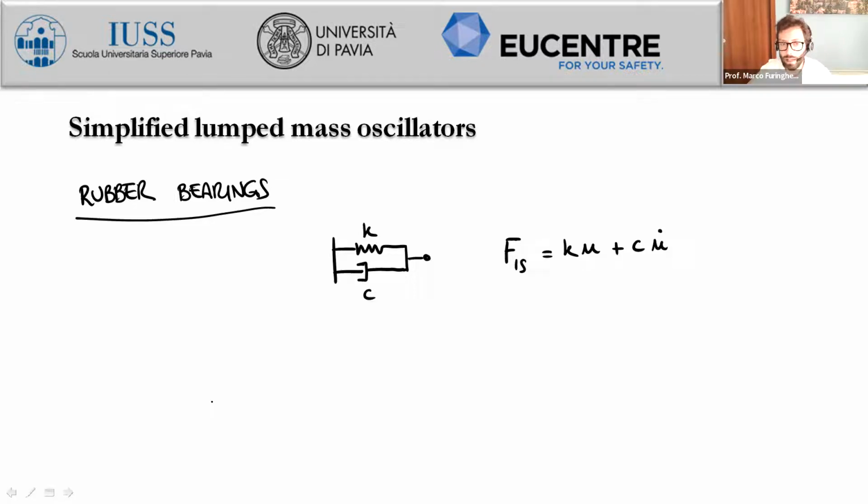Okay, here we will have actually the C value, which is returned directly by the typology of the rubber compound, and we have seen different damping ratios related to different compounds: medium, soft, and hard compounds. So we have seen how to define both the K value and also the C value. For rubber bearings, we will have generally a number of isolation devices. So we will have just N isolation, which is the number of isolation devices for us.